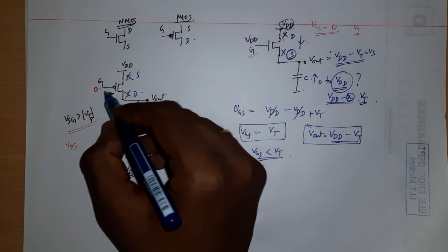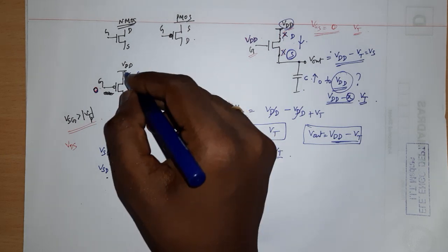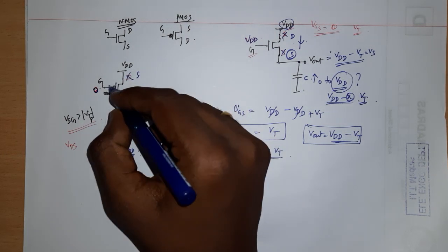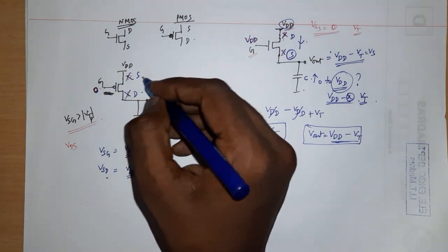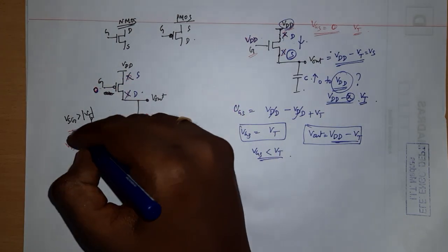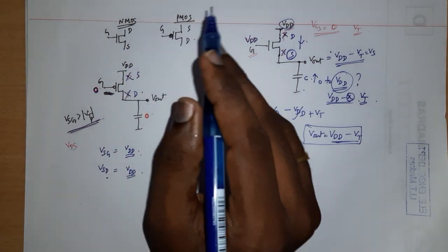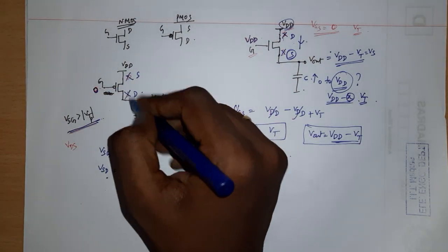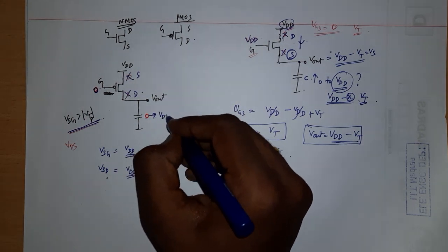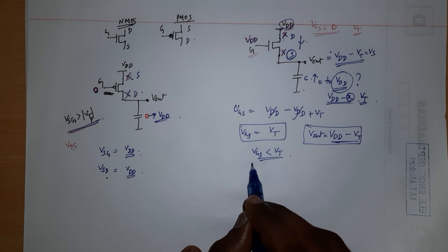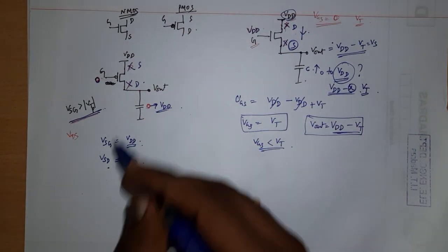As long as the gate voltage is 0, the source will pass the VDD here, and VSG will always remain at VDD, which is much higher than the modulus of VTP. So this will always conduct, and all the VDD will appear at the output, so 0 will turn to VDD. This is something that is desirable for me.